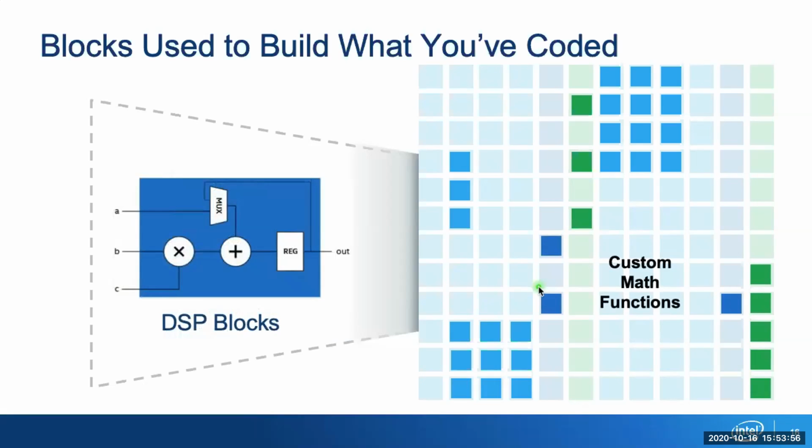And we also have DSP blocks, which means digital signal processing blocks. Some mathematical functions such as addition and multiplication are available in dedicated hardware blocks, and compilers are able to infer and instantiate these blocks instead of building operations using conventional logic with the logic elements that I just mentioned.